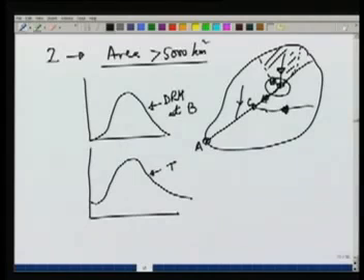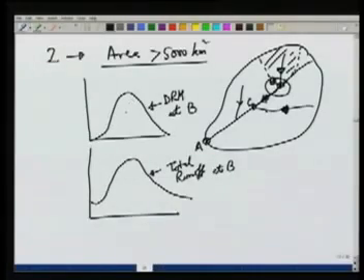To get the total runoff. So these two steps can be done using the unit hydrograph theory, because at B the catchment area is small enough for us to apply the unit hydrograph theory. So this DRH can be obtained knowing the intensity of a storm in this area B, and then total runoff can be computed at B.